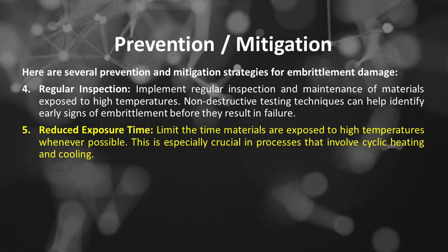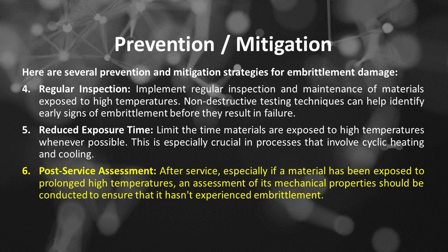Number 5 is reduced exposure time. Limit the time materials are exposed to high temperatures whenever possible. This is especially crucial in processes that involve cyclic heating and cooling. Number 6 is post-service assessment. After service, especially if a material has been exposed to prolonged high temperatures, an assessment of its mechanical properties should be conducted to ensure that it hasn't experienced embrittlement.